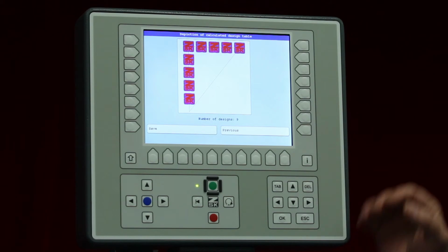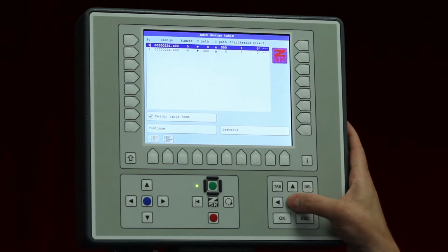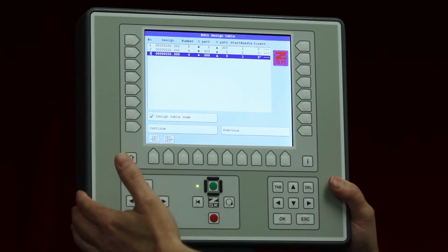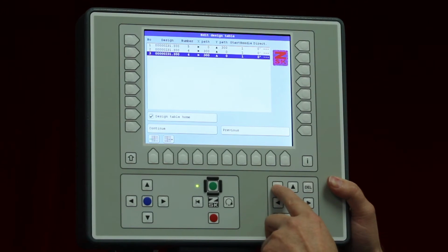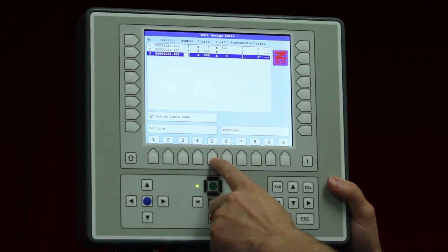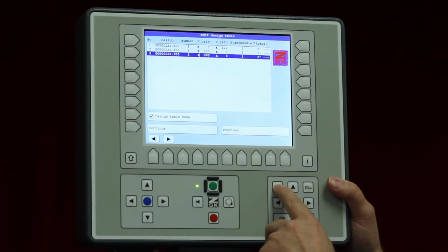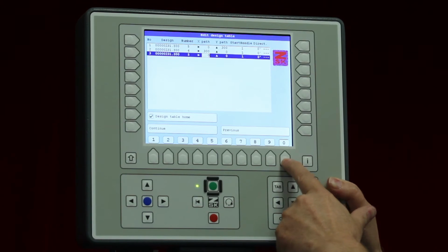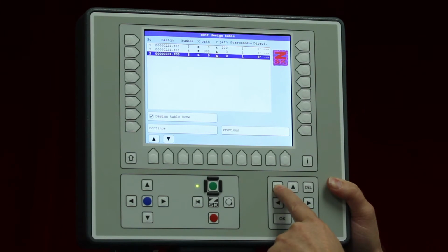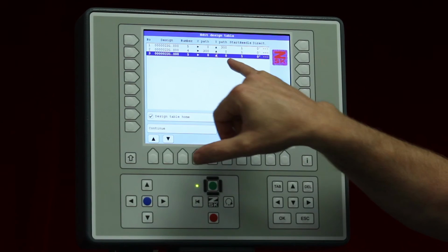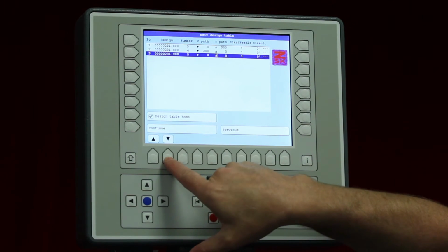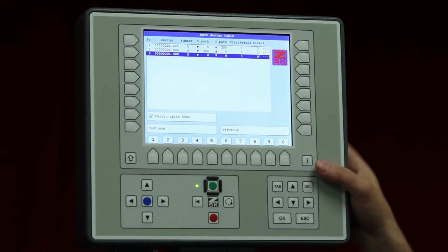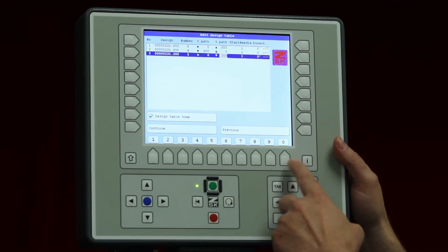Almost finished. Previous. We go down and we have to insert another line, pressing the button U1. Same design, this is okay. Now I need a repetition 5 to go down. I don't want to use the X path, that means the horizontal one, so I press 0. Don't make any movement, but I want to go down. And you see the arrow shows me up. So I use now the button down, it changes. And I want to go down 300 increments, 300.